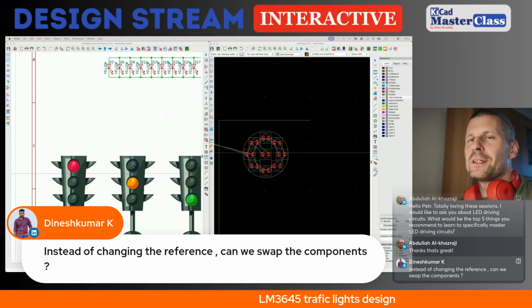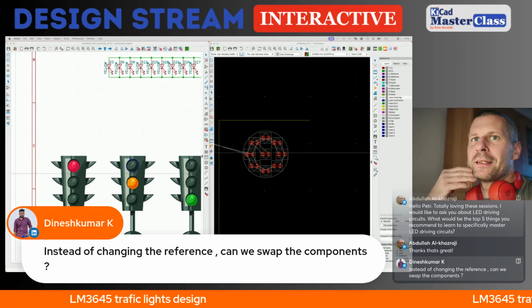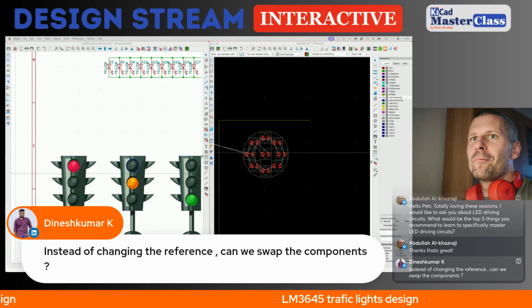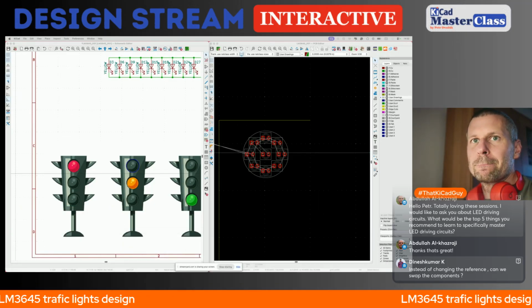So these newly added components have the unassigned component designator. So you either have to update the schematic or the PCB, and I chose the PCB.